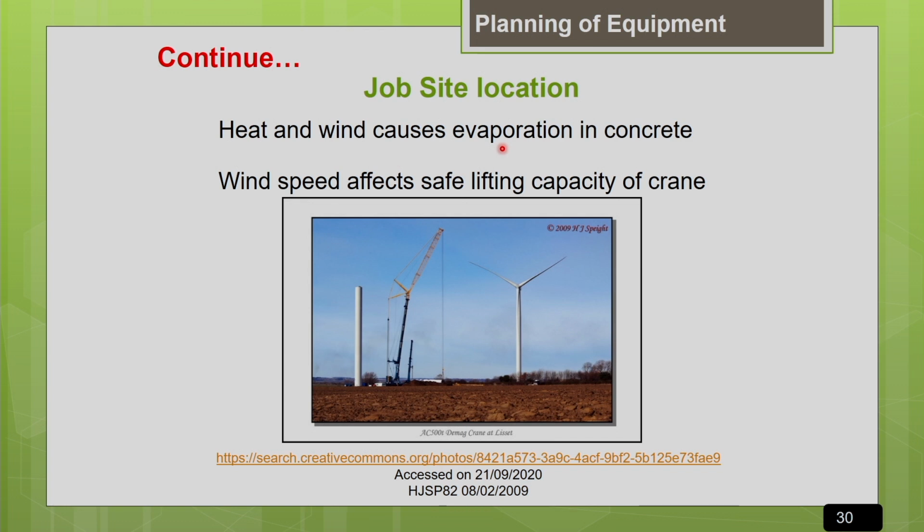So in those places, you should have some facility to protect the concrete during the making of concrete, and even after the concrete is made, it should be properly protected from severe weather conditions. And you should start the curing of concrete as early as possible in aggressive conditions to protect the concrete from cracking. And another important factor which will affect the selection of machine, particularly the crane selection, is